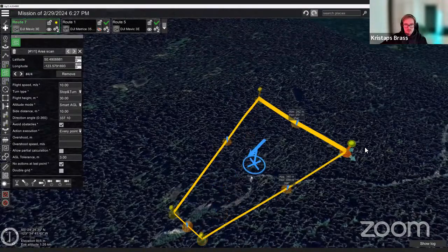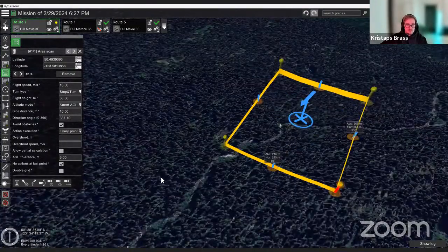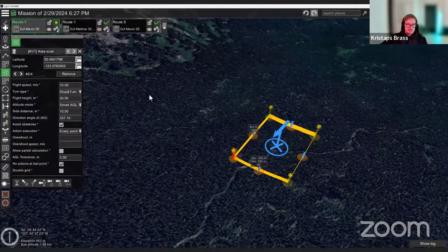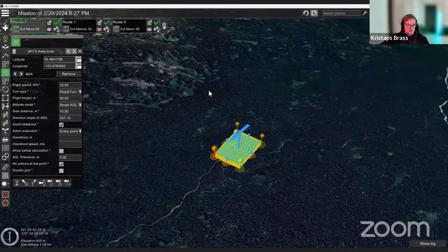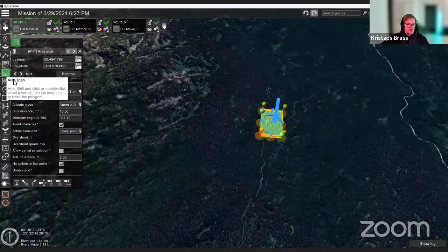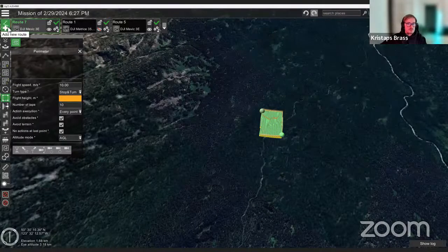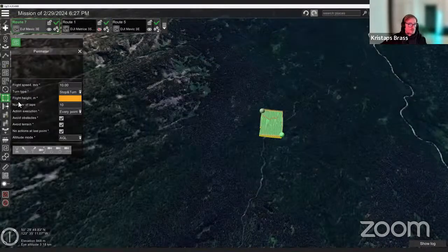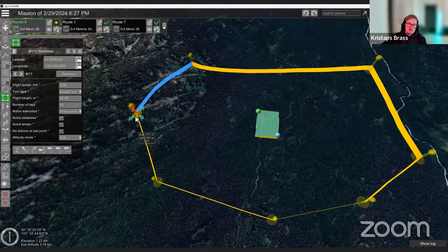And you can also increase the size. Well, actually, how I would cover very large areas with drones. So, for example, firstly, I would mark out the borders of the area. And this you can do either by planning some very simple mission in UgCS or by importing the same KML file. For example, if I use the perimeter tool in a separate route, I can mark out the exact area like so.